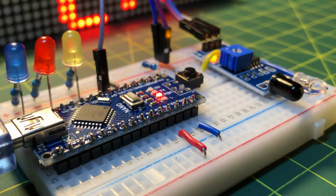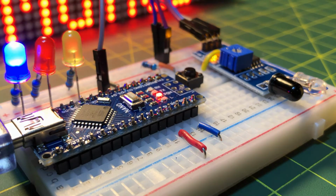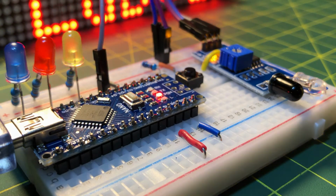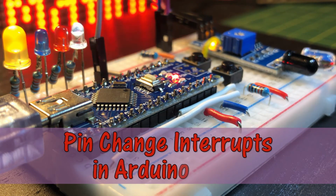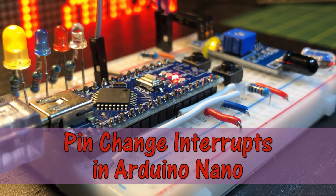We saw in a previous video that the Arduino has two external interrupts, which is a limitation if your project requires more. In this video, pin change interrupts are presented. PCI will enable the Arduino project to have up to 22 hardware interrupts.